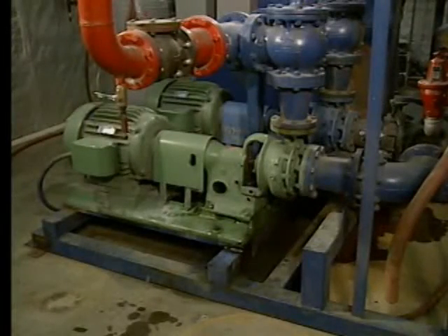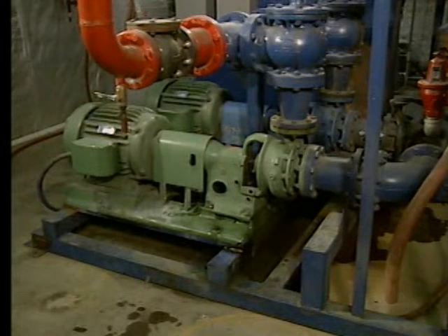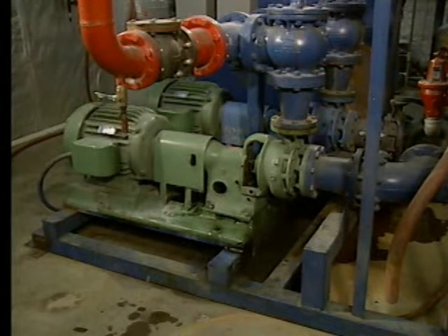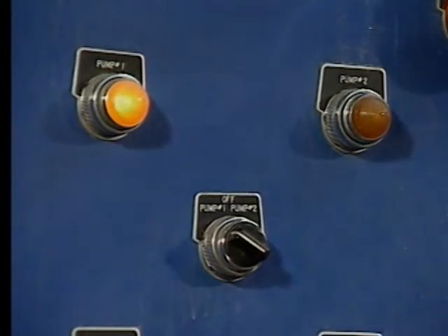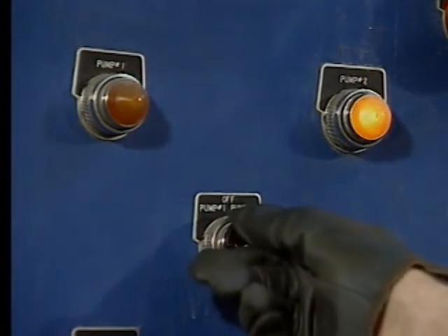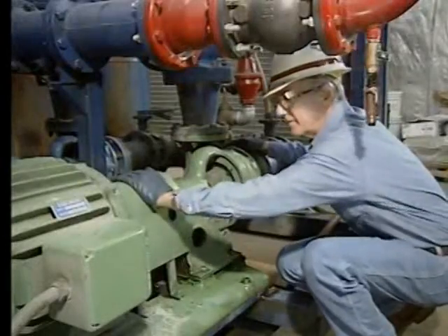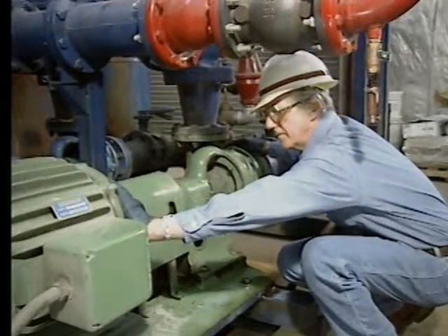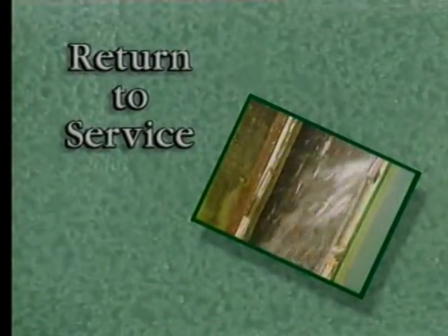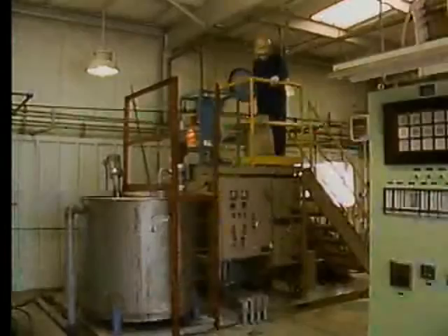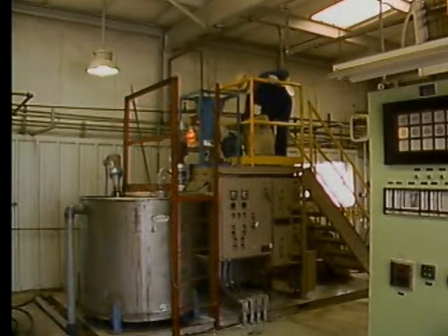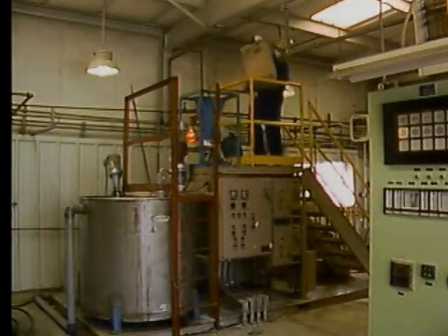Further investigation shows that the pump that supplies water to the water spray system has broken down. This is the cause of the problem. To correct the problem, the operator has a backup water spray pump started. He also reports the broken pump so that it can be repaired. At this point, the cause of the problem has been found and corrected, and the operator can return the system to normal operation. To do this, the operator readjusts the pH of the water leaving the treatment system.